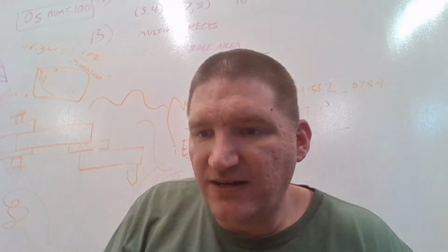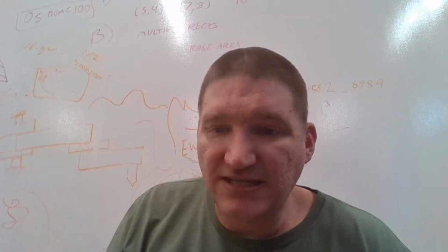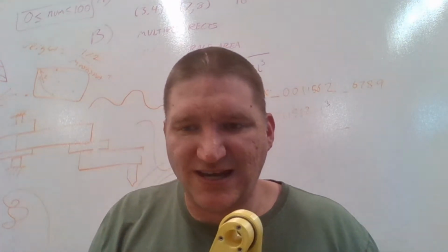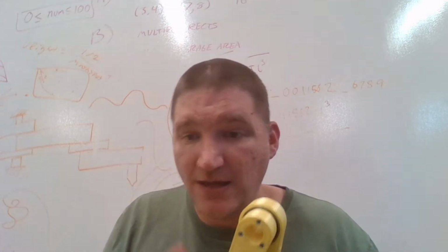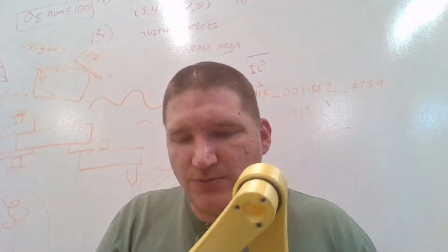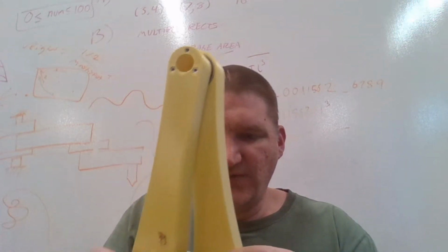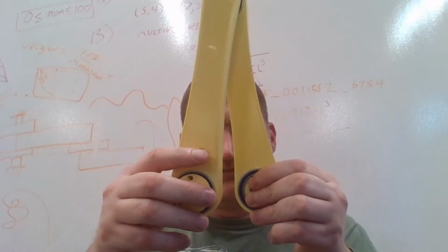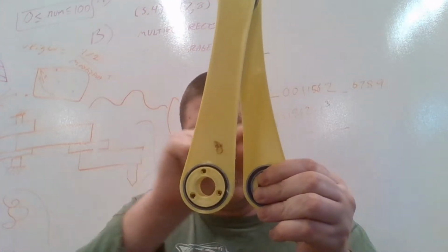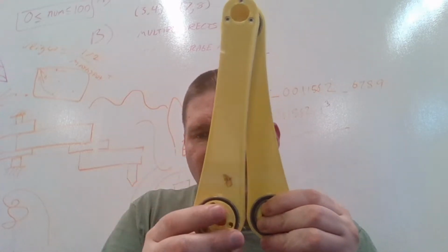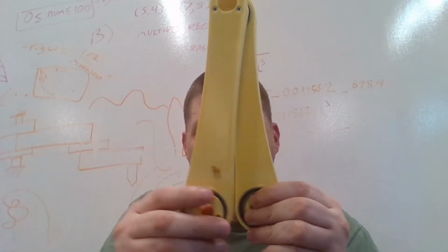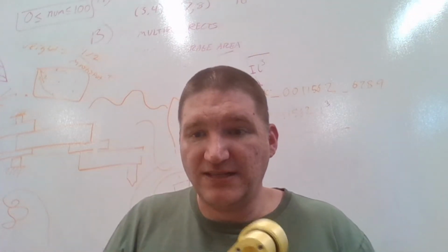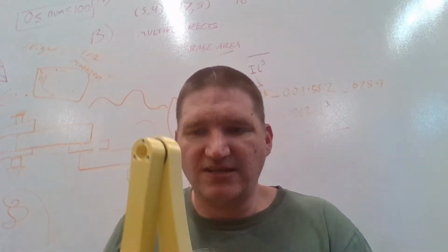Any ideas for varying arm lengths in the same machine? Yeah, in the MonoRail video, I actually had 2 different arm lengths to keep the elbows from knocking. And so yeah, you could do that. The problem is if you have different arm lengths, you can't get close. You exclude a region around the pivot that you can't get to. So if the arm lengths are the same, you can get as close as you want. So the basic idea is to have the same arm lengths. But from one set of arms to the other set of arms, you can have different lengths.